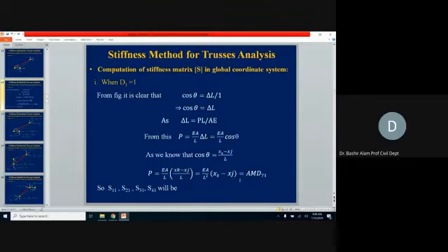And actually, this member force is our AMD in member 7 because of the displacement in one direction. This is how we write the description of this AMD, the member end force. Meanwhile, we are generating our AMD matrix also, and its notation will be AMD 71. 7 is coming from the member number and 1 is coming from the direction where we are giving the displacement.